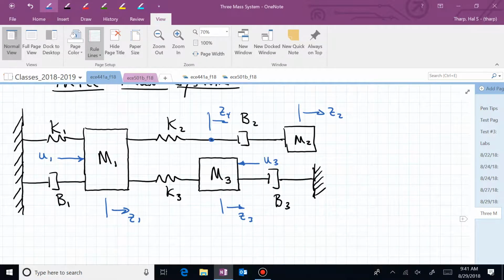If I now move in the positive z sub 3 direction relative to b sub 3, that dash pot, what needs to multiply b sub 3, expression-wise? One of the ends of that dash pot is fixed, is it not? So we really just have one variable. And if we move in the z sub 3's positive direction, the way that we created the positive force associated with dash pot 3 to the left gives us b sub 3 z sub 3 prime.